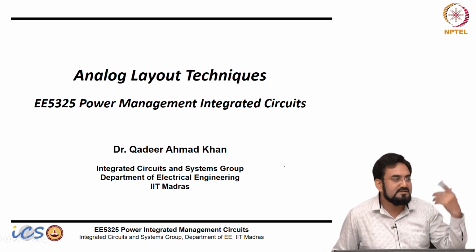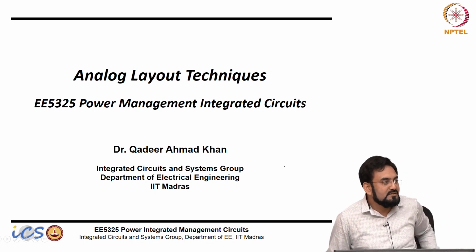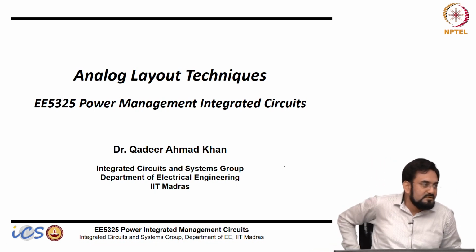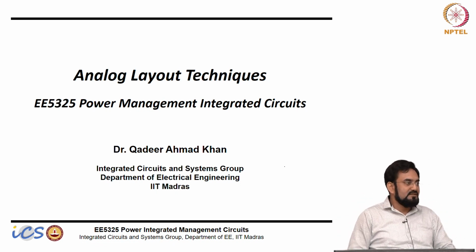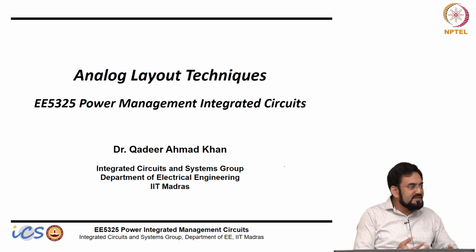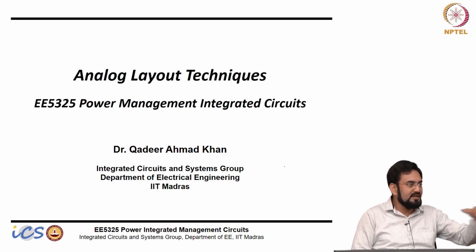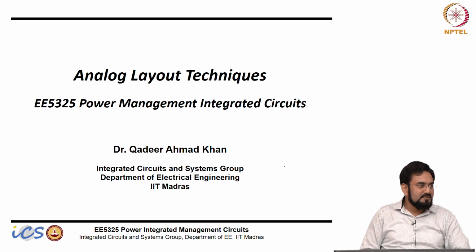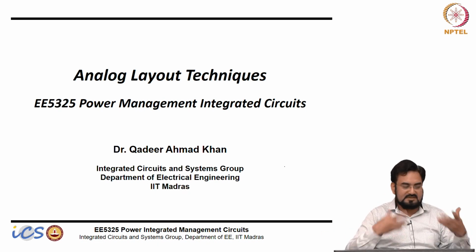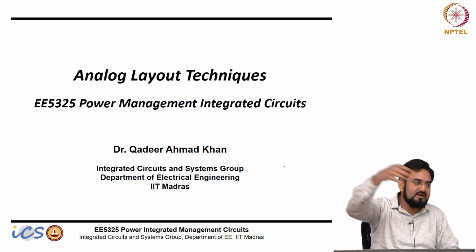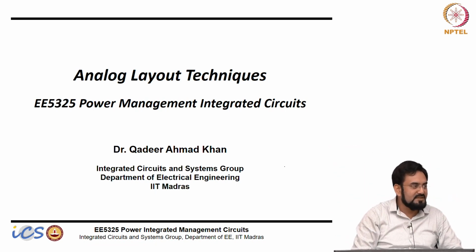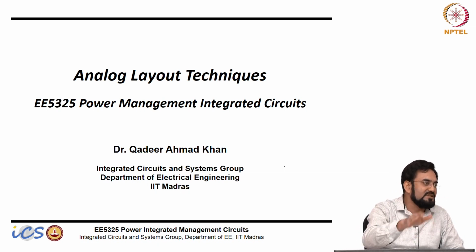No. Anybody else? What is layout? Can you send your schematic to the Fab? Huh? The Fab doesn't understand schematic. Layout tells you how the mask will be created, layer by layer. That's it. Placement, routing, all those, your Fab will not understand. Whether you place at this corner or that corner doesn't matter for the Fab. It's only the information of the layer masks that will be created.